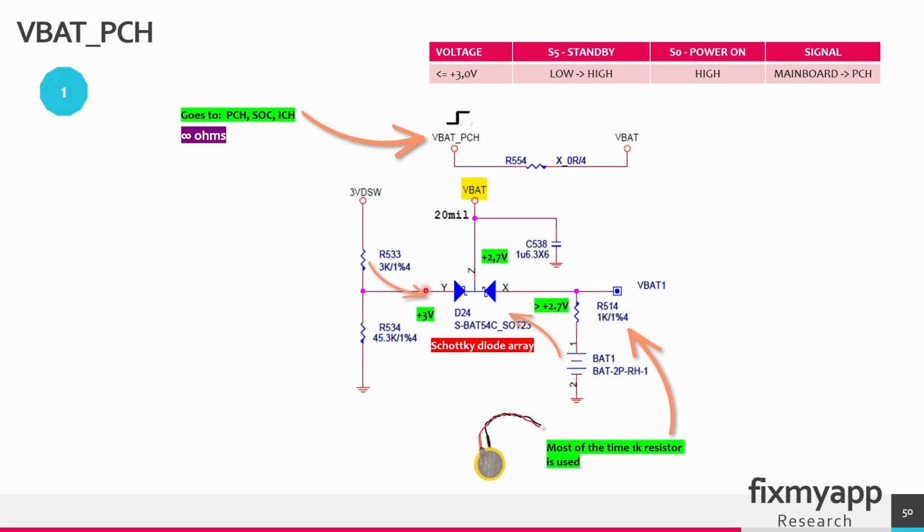The common cathode configuration means that the cathode of these 2 Schottky diodes are shared. One anode is connected to the battery and the other one is connected to the 3.3 standby voltage. The diode connected to this regulator will be forward biased because the anode is connected to the output of the regulator, and this voltage is higher than the cathode voltage of the feedback. The current will flow from the regulator through the diode to the feedback power line. The feedback diode will be reverse biased because the feedback is at a lower voltage, so no current can flow from the battery to the feedback voltage rail.